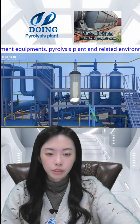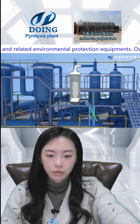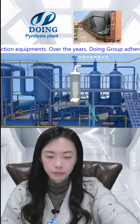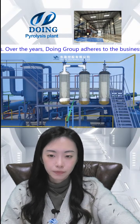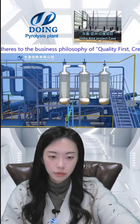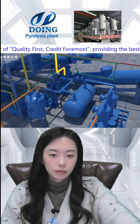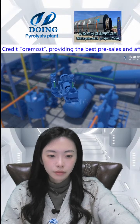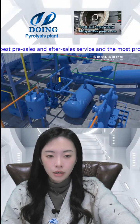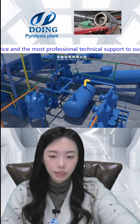Next we come to the vertical condensers, which are used to increase the cooling area and ensure that all the oil gas is cooled down. They have several tubes inside, and the oil goes through the tubes, with cooling water outside. All the water is also recycled. This is the negative pressure device, a micro-negative pressure process to reduce the contact between the carbon black and oil gas.